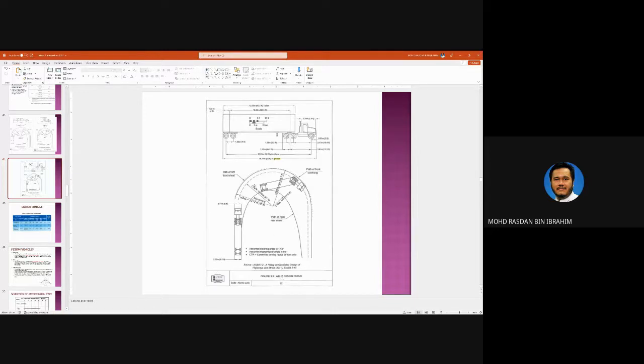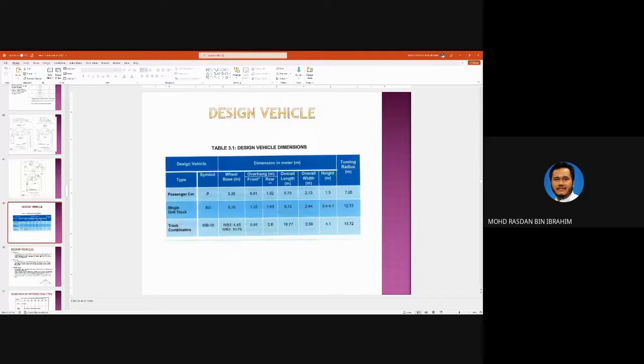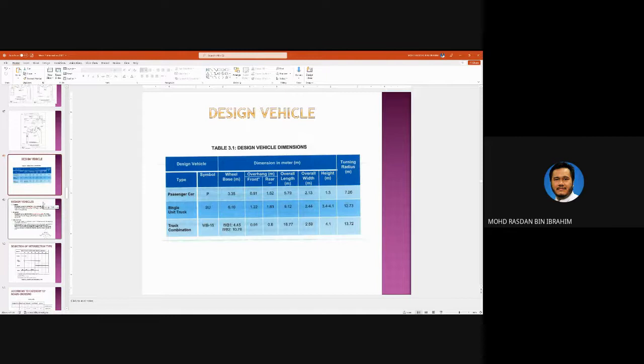50 feet wheelbase. So the path of overhang is even bigger, 12.5, and now here it is almost 14. That's 1.5 meters beyond the center line turning radius here. So these are the dimensions for the design vehicle.